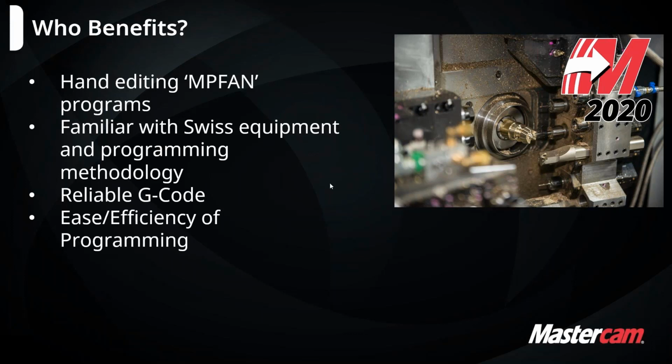And the next is what I was talking about before, just the ease and efficiency of Mastercam programming. That's the nice part about Mastercam: I can get into the weeds and set up my stock and my jaws and 3D tools and really go down that route, or I can draw a 2D profile in 5 seconds and slap a generic tool on there with the correct insert, and I can have G-code in 60 seconds. So that's the nice flexibility that Mastercam offers, both ends of that spectrum as far as how much job setup and process planning you want to do before you're actually getting a program out to the machine to make some chips.